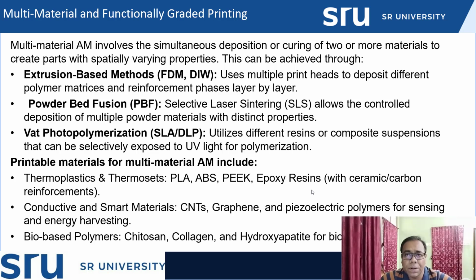In that case, the DMLS technique or SLS process can be used. One can use a certain layer of powder having certain properties, and similarly another layer of powder with other properties. Or some other powder can be used, or that powder can behave differently after solidification than the other layers. In this way one can make the functionally graded composite material.